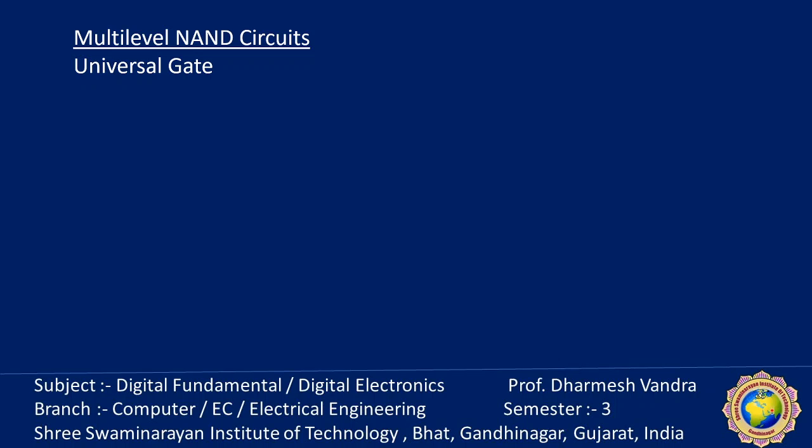While if the same thing is designed and converted into NAND, only NAND gates are required to complete the design of any combinational circuit. And NAND gates are available in particular ICs, so there is no requirement for different types of ICs. So circuit size also reduces and functionality becomes easy.